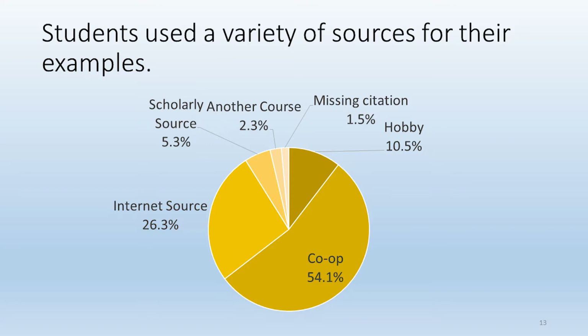Both on their surface are ovens that need to control temperature, but have very, very different control schemes, because for us, when we heat up the oven in our kitchen, what do we do when that bell goes off? We open the door and let all the heat out. So in that particular case, we design the controller to overshoot. We don't care if it goes up to 450 degrees if we set it to 400, because we're going to let a bunch of heat out to put our pizza or cookies in. Or, we're almost to Thanksgiving, put our Thanksgiving turkey in.